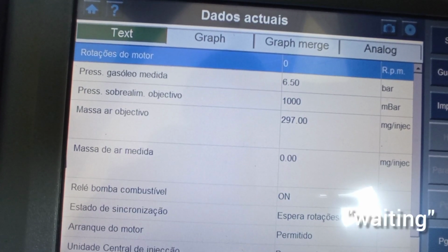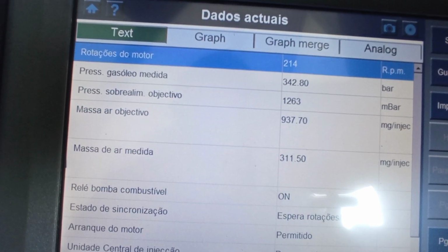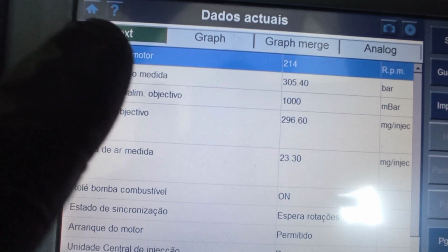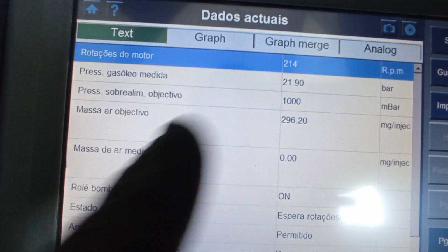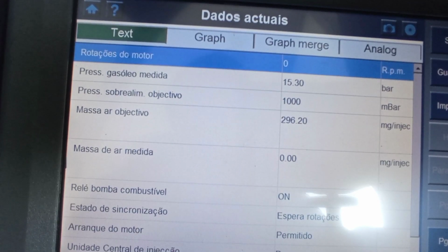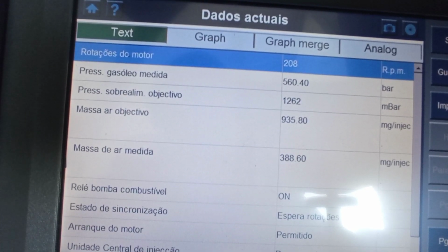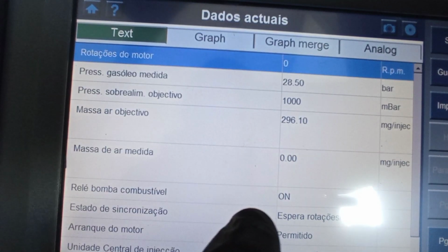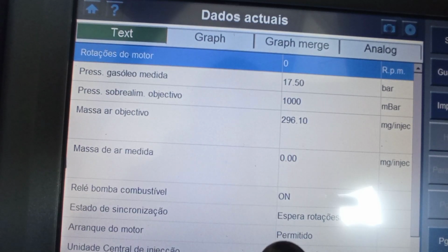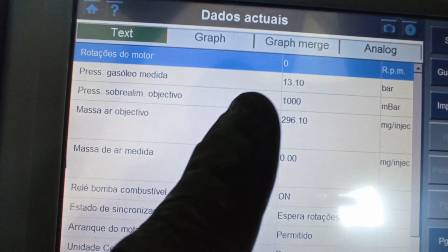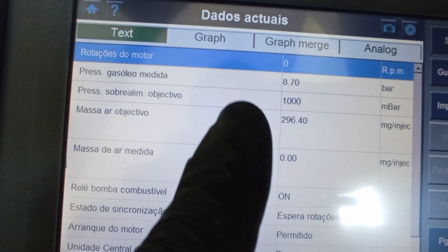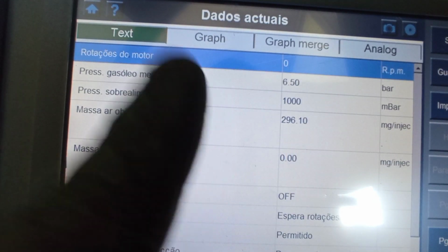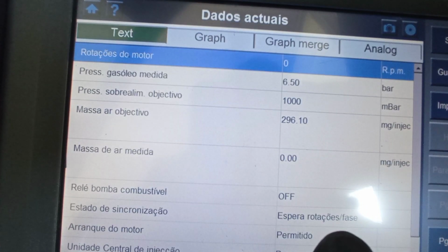Okay, crank. So we have fuel pressure, but it takes a long time to develop. Again. My starter is getting tired. It actually starts to develop a lot more fuel pressure because of the time that we are cranking. So on the RPM, we have 0, but after some time it starts to do some magic over there. Yes, magic. And over here, on the synchronization, no synchronization.